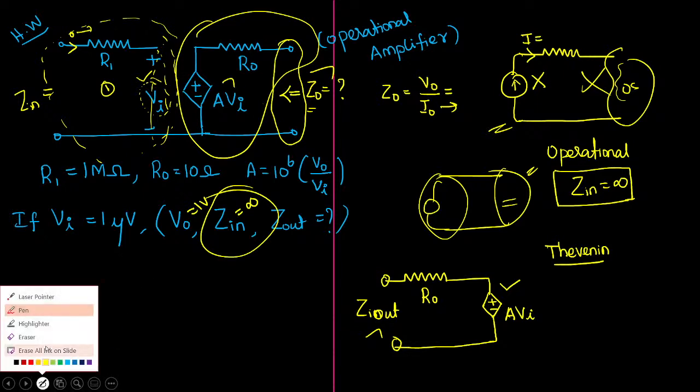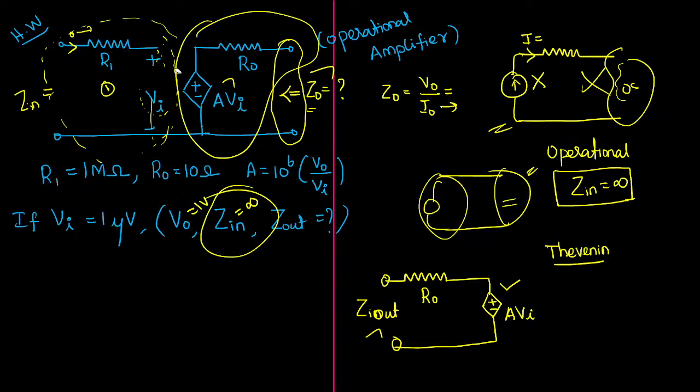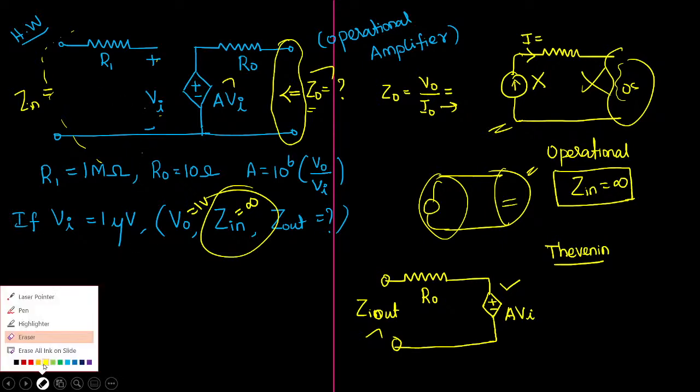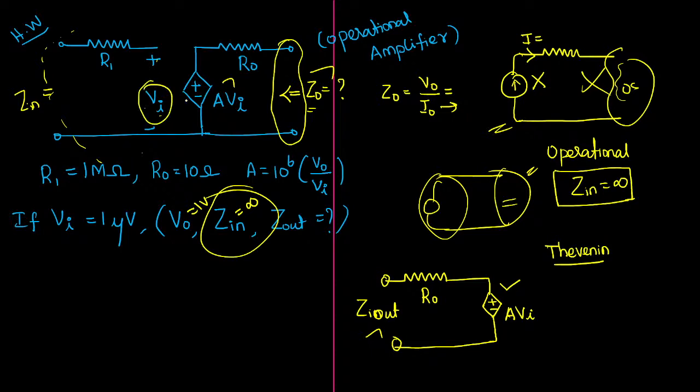Now see whether an independent source is present in our circuit. Do we have an independent source anywhere here? Yes, sir. On the input side, a voltage is given, and basically they have given only its polarity, not any symbol. It means that is an independent voltage. There may be some battery behind this. So we have to deactivate the independent voltage. Deactivating means I have to short circuit the voltage source. When I short circuit the voltage source, the input voltage becomes 0 voltage, or not? Yes, it is 0. When VI is 0, I can replace VI here also by 0.